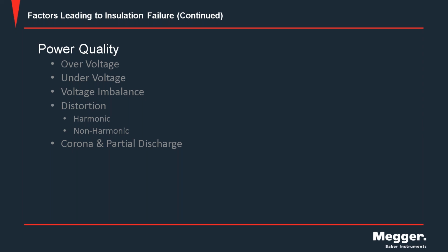It comes down to the design of the motor. If there's voids in the insulation, for example, that can lead to internal partial discharge, which will cause acids to form internally and then eventually lead to turn-to-turn or turn-to-ground internal failures. So being able to detect partial discharge activity is also another important element of a motor testing program.